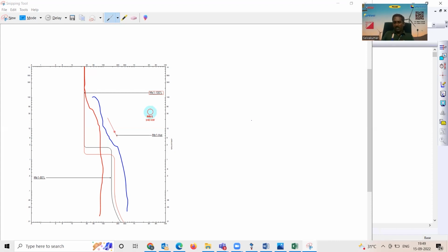Breaking of a contactor will not really break the fault current. So when you have a contactor, definitely you have to go for a fuse. Overcurrent or overload protection is provided by your contactor, 49 and 51. But 50 you will disable in that particular relay, and 50 is basically taken by the fuse. Even if you enable 50, the fuse will operate in 3-4 milliseconds, which will not wait for the relay to respond to a fault.